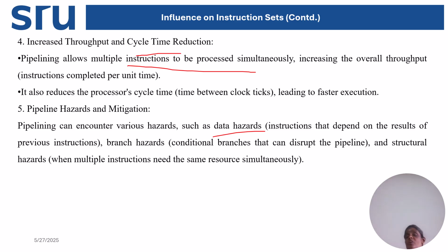Suppose the addition is performed in a delayed manner, the data available for input will be some other data and not the output of the first instruction. That is the data dependency between two instructions, and if it goes wrong, it is named a data hazard. See, it is the dependence on the results of the previous instruction.